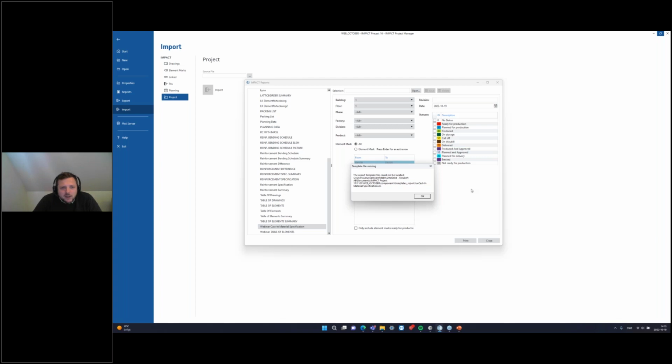This is happening when you have an existing project, as I have here, and then in the meantime that this project exists, you create this report, which I did earlier today. Then we don't have all the files in the folder for the project. So you see that the template file is missing. How to solve it is pretty simple. We just right-click, update template, and print again.